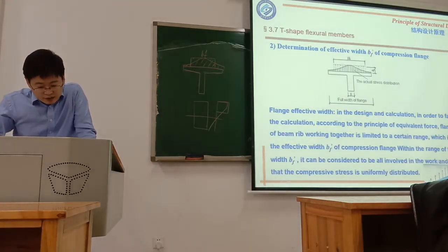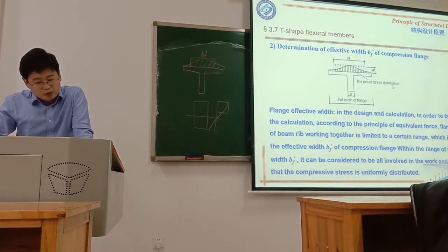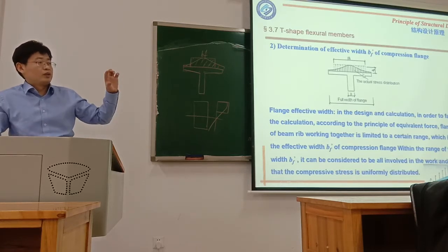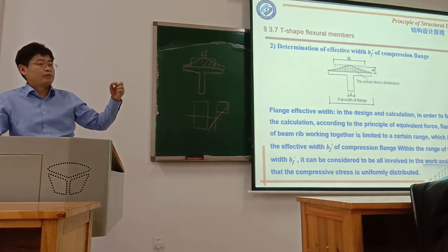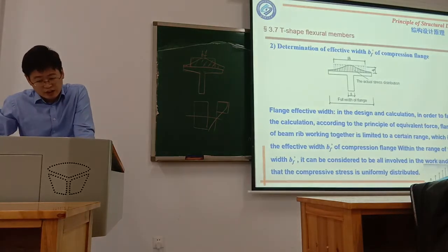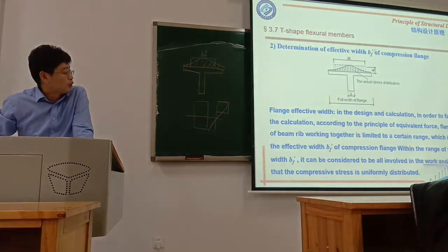This curve is the real actual stress distribution. Now we want to get this equivalent width b_f'. Use this rectangular shape to replace the real distribution. Keep the total force the same, but make the calculation simple. Now the question is, how to calculate this b_f'?